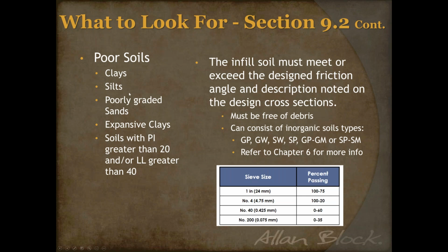So if you've got clays, silts, poorly graded sands, expansive clays, or soils that range depending on their PI (plasticity index) and LL (liquid limit), that will all depend and vary on your soils, but those will all play a big role in global stability and retaining wall designs.